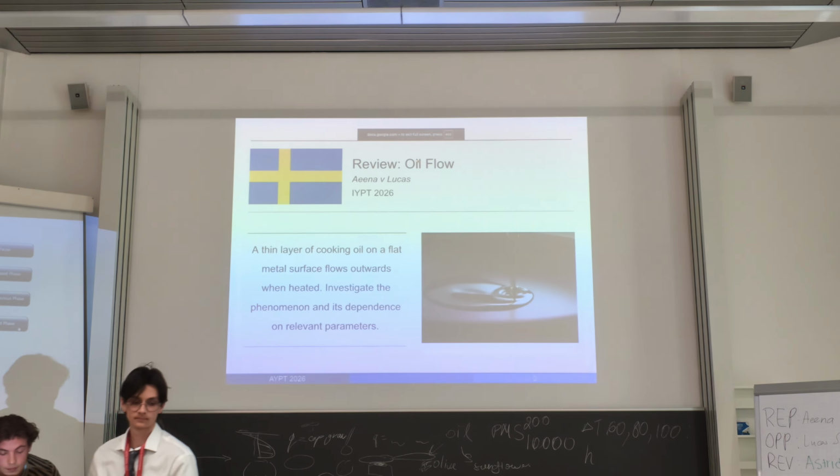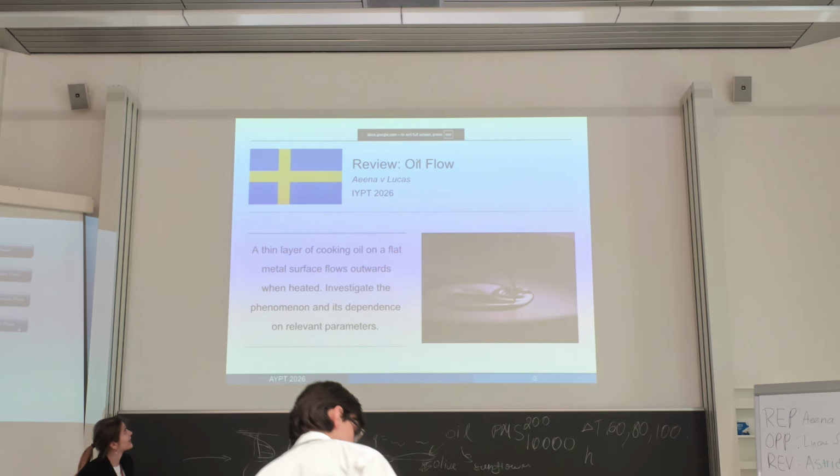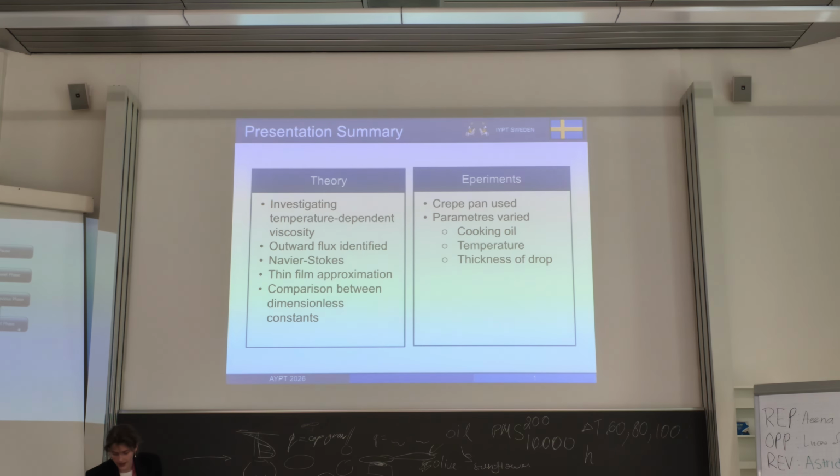Okay, go ahead. Hello, today I'll be reviewing problem 4, oil flow. So just to summarize the presentation, from what we could tell, the reporter was investigating temperature-dependent viscosity in the oil, and through certain equations identified a term for outward flux, and was also using the Navier-Stokes equation to describe the motion. They used the thin film approximation to further develop their model, and also made a comparison between different dimensionless constants in relation to the phenomenon.